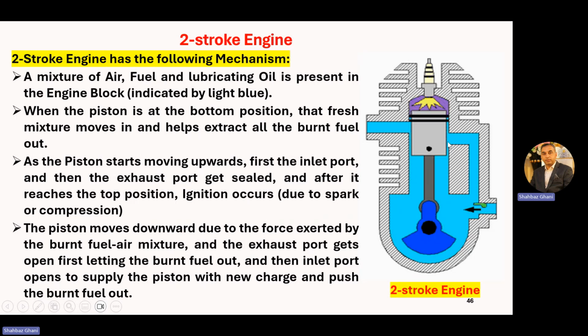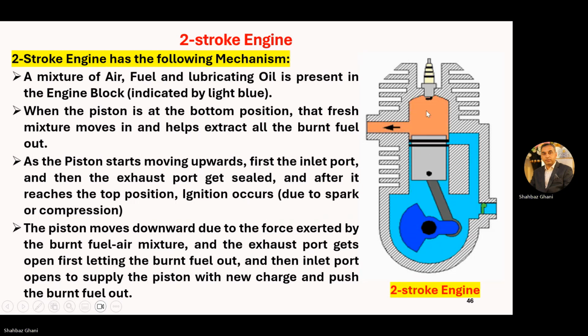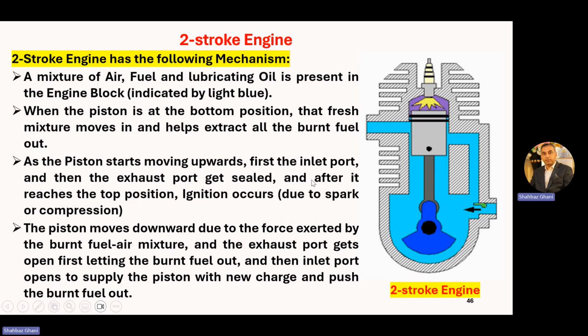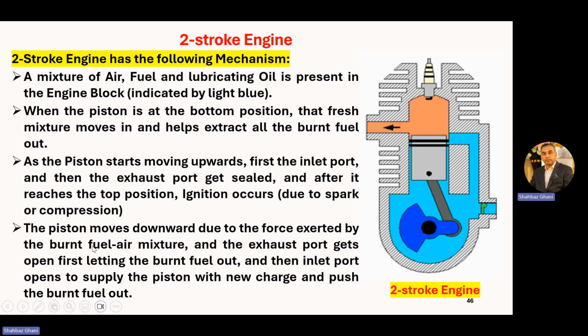Piston is moving from BDC to TDC. Your inlet port is closing, then your exhaust port is closing, and you have a compression here. And after it reaches the top position, ignition occurs due to a spark or a compression. The piston moves downward due to the force exerted by the burnt fuel-air mixture, and the exhaust port gets open first. When the piston is moving from TDC to BDC, first the exhaust port is uncovered.